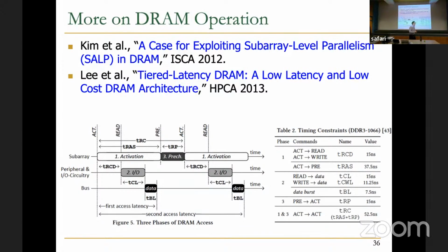But you can also say that, okay, maybe I don't have a single timing constraint. I just have an asynchronous interface. So timing constraint, by definition, implies a synchronous interface. You basically know how long something is going to take. And based on that, you design the memory controller to take the next action, right? But you can say, forget about these timing constraints. I just want to be asynchronous, meaning the memory controller sends a request, and the DRAM returns the request using some acknowledgement. It could be any time. There's no single timing constraint. It could be 5 cycles if the request takes 5 cycles. It could be 215 cycles if the request takes 215 cycles. Now that's becoming more interesting, right? That's a much more flexible interface compared to this very nitty-gritty synchronous interface.